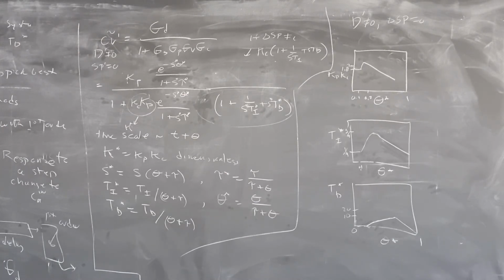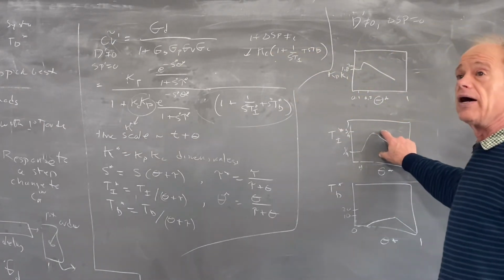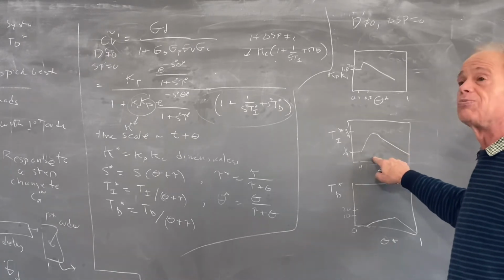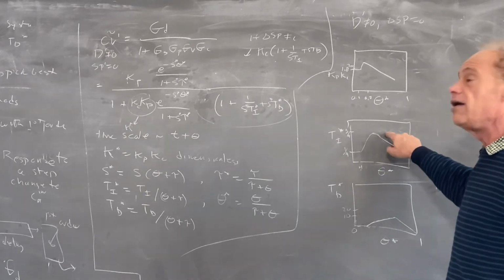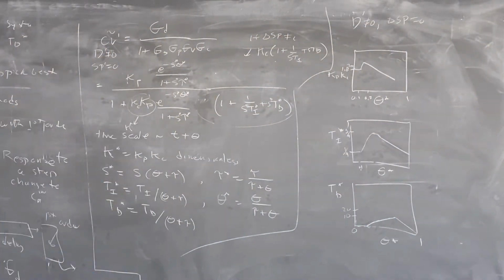The other thing to notice is this has a fairly small range, TI. It's easy to make TI too small. You make it too small, things are aggressive. You make it too big. Actually, let's just look at that for a second. I think I explained TI upside down, so let me go through and redo TI.